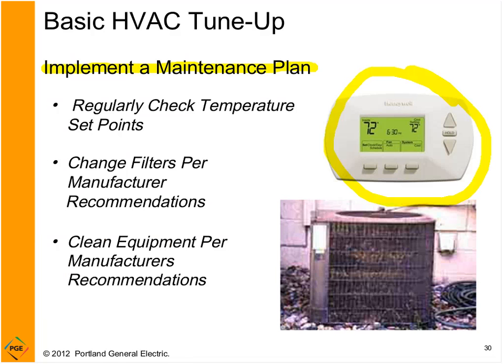And so regularly check the thermostats. Most of you, if you have a thermostat, it's going to be a programmable one. If you've got an older style, non-programmable, the round dial, I would encourage you to change it out to a programmable system. You do have to be a little bit careful to make sure that you find a thermostat that can work with the equipment that you have in operation, but the packaging and the specifications for the thermostats are pretty good at telling you what type of thermostat works well for what piece of equipment.